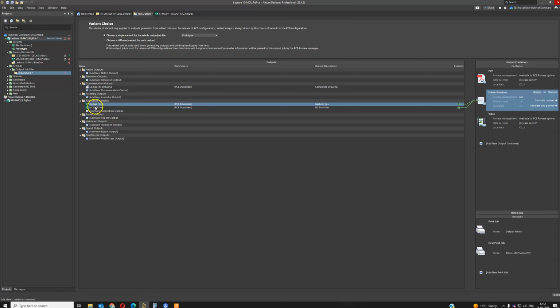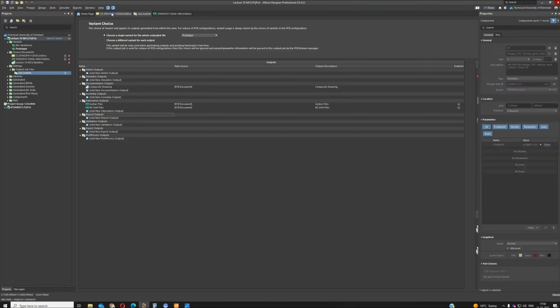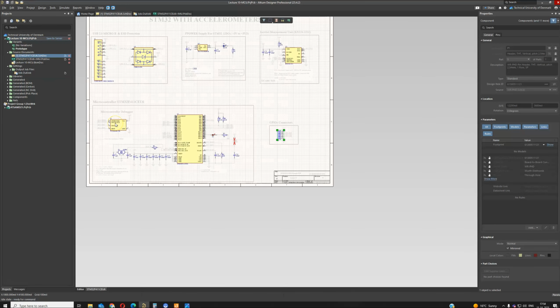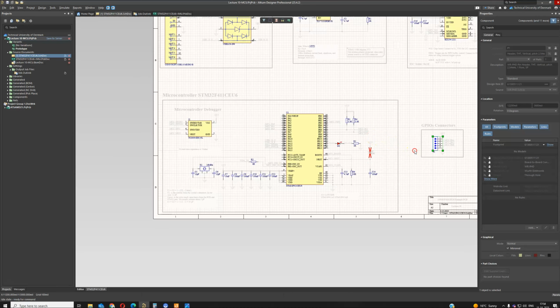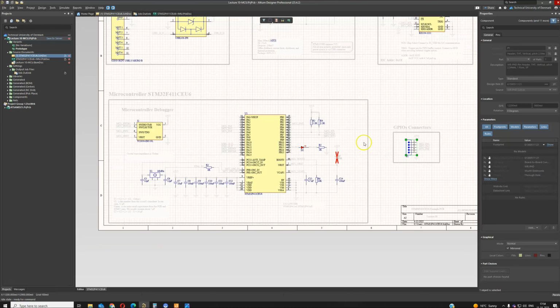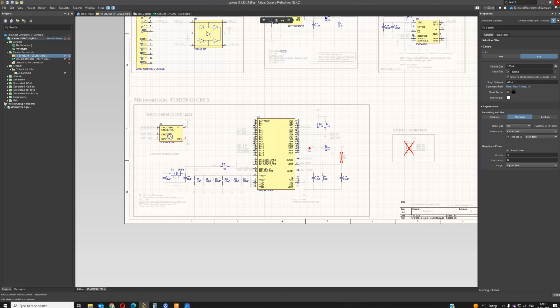So now we're done with these Gerber files. So let's do the rest of the files. And before I do the rest, like this connector, they don't have it at JLCPCB for sure. And normally I don't make them place the headers, so I will also remove those from my pick and place and from my BOM file. So save.